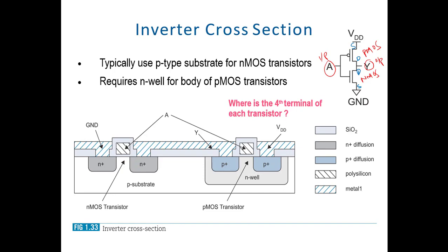If you look at this, here we have the NMOS and here we have the PMOS. We start with the P substrate, which is our first thing. It is like mechanical support for the whole thing, and we start to develop different areas. For example, this area is our doped area, and it has an abundance of electrons.